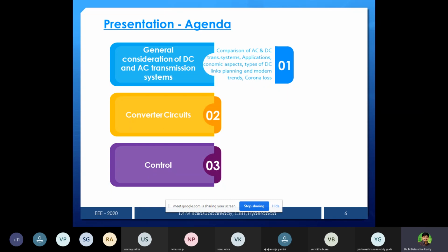And here, suppose it is a 6 pulse converter, we will use 6 devices, 1 3 5 and then 4 6 2, and these are connected to, suppose, A phase, then B phase, then C phase. These are the valves, 1 3 5 4 6 2. But strictly speaking, this is not one device. In general, in case of HVDC transmission, whatever I mentioned, 1 3 5 4 6 2, it is not one device, it is a combination of devices.